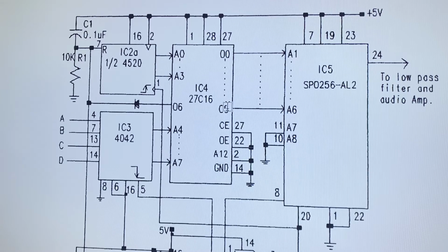So if you only scan this, and the latch, which controls address 4 and address 7, is equal to 0, the counter will start scanning from location 0 through 16. If you want to scan another block of memory, you have to enter data here. So you enter number 11000, and you store it with the latch clock here.